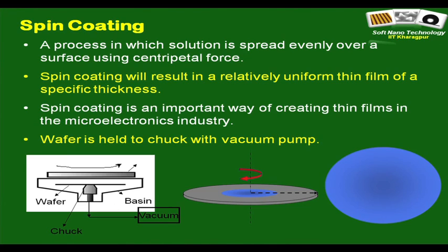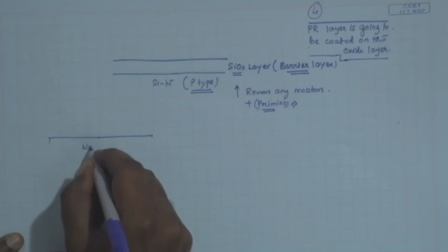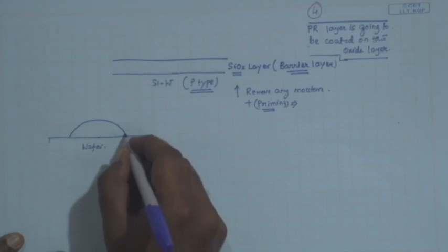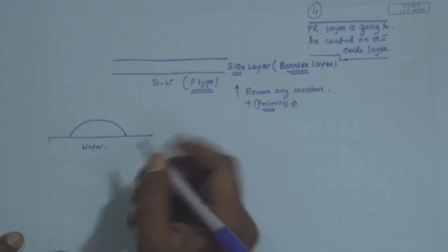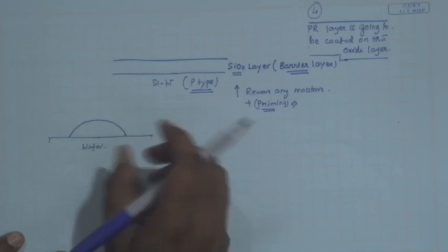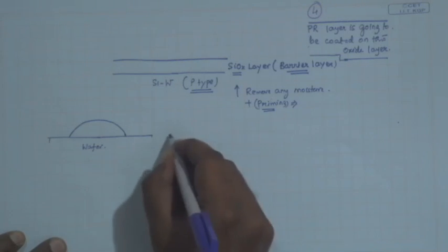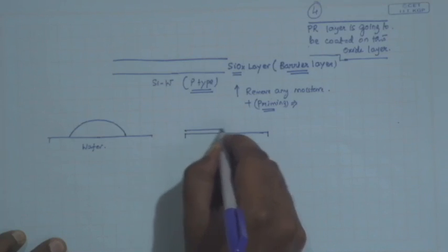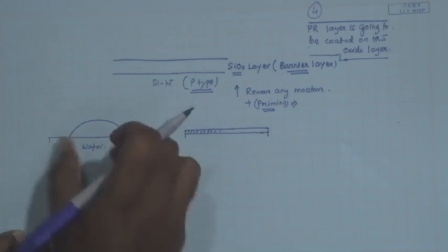Suppose this is your wafer and you dispense your solvent solution, which let us say makes a finite contact angle. Since you know Young's equation, you know that this corresponds to a partially wetting configuration, not a fully wetting one, but you would like a film that covers the entire wafer surface. So you would like to spread this drop.